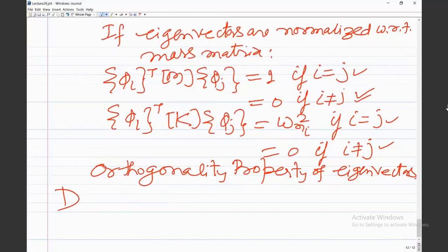Okay, sir. But assembly, of course, if you have formulated an element in the physical coordinate itself, you have assumed the variables in terms of the physical coordinates x and y, and if you have the mass matrix, the assembly is the same. The assembly procedure would be the same, whether the element is an isoparametric element formulated in natural coordinate space or an element formulated in physical coordinate space. So the assembly is going to be the same.